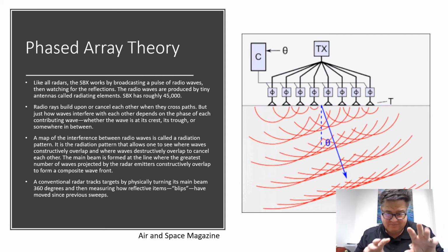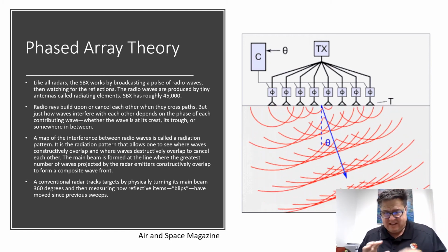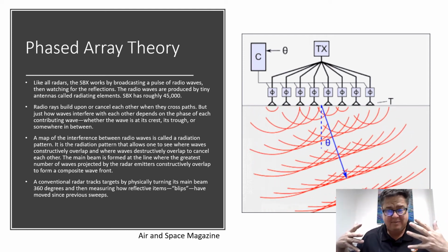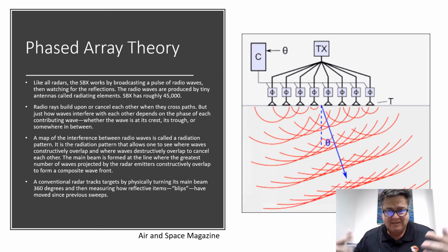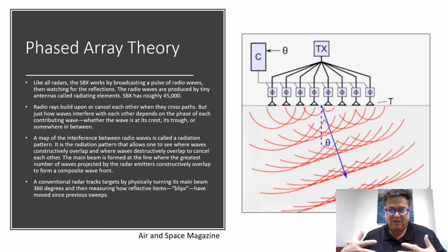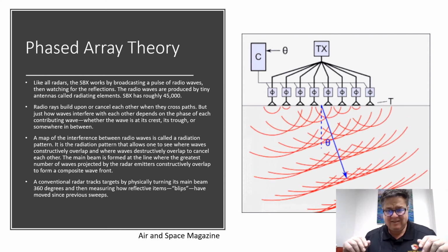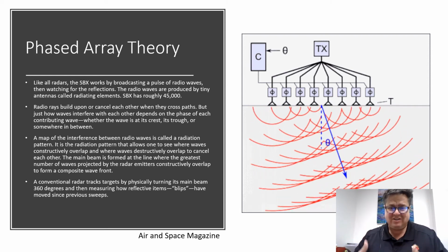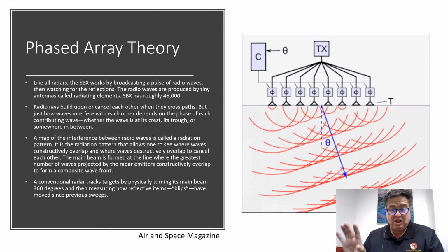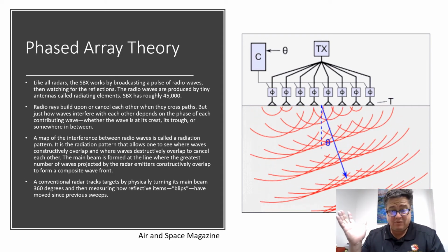These little pencils. They're all sticking out in that panel, and there's a computer that creates an electronic wavefront by adjusting the timing of how the signals emit out of these emitters and knowing when the collisions of these two waves are happening so that they can have null and wavefronts that occur, and we can direct them at a target. And so it's really neat. It's a radar that you can adjust its pattern of how it's emitting without ever moving the radar.